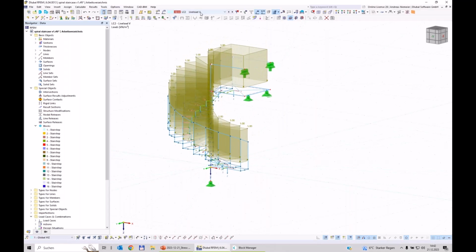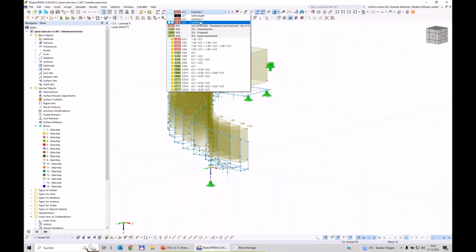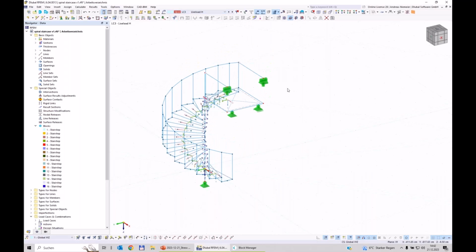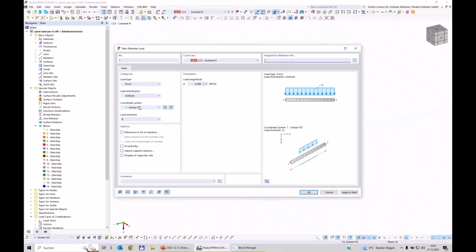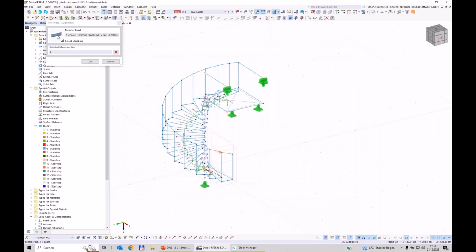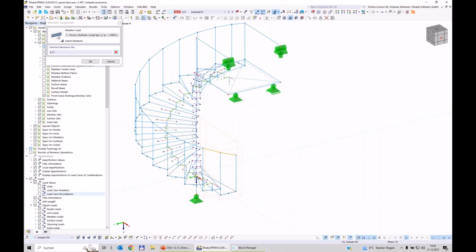The same for the horizontal. So here I only have to select the members. So I use a member load. Let's use, for example, here in local direction, in Y direction, -1 kilonewton per meter. And here I pick, so if you don't want to see these bounding boxes, you can go into the display navigator and say, okay, this bounding box should be deactivated.